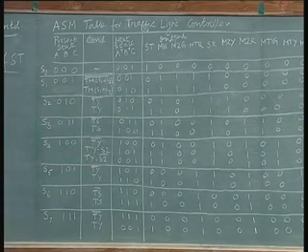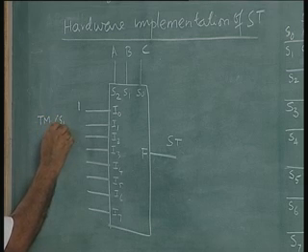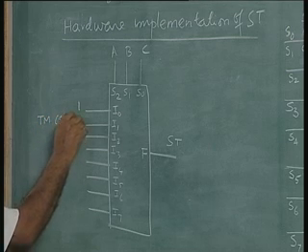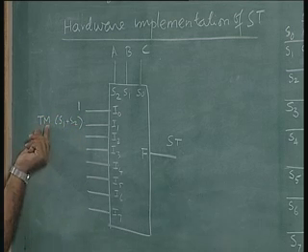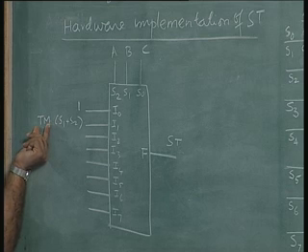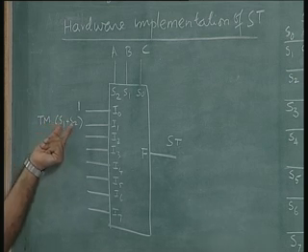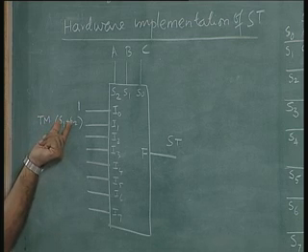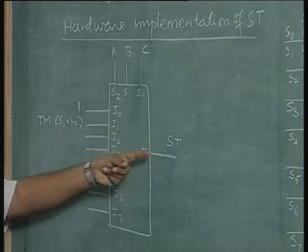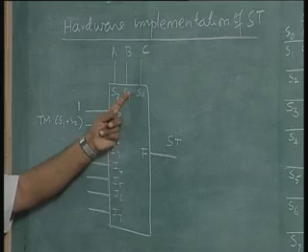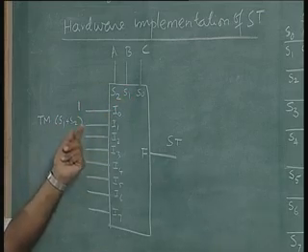So for I1 I will have to put Tm (S1 or S2). That means after the elapse of the time Tm, the main road green time, and if one of the sensors is true, then the start timer will be initiated when you are in state 1. This is how you map it.